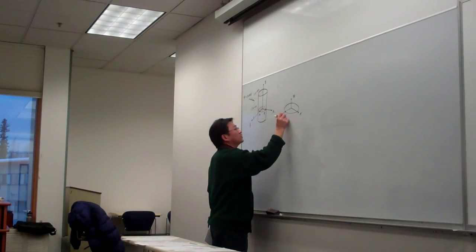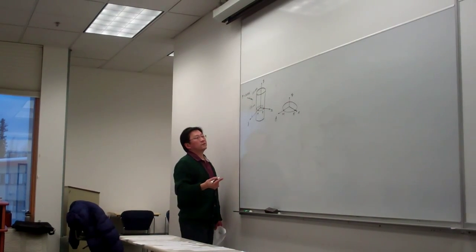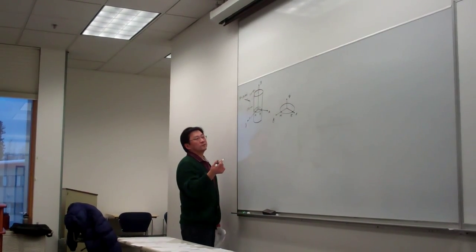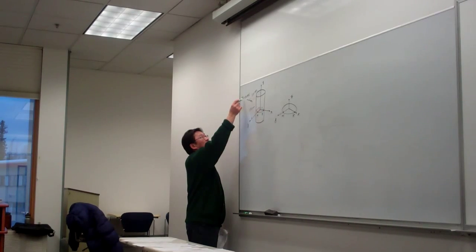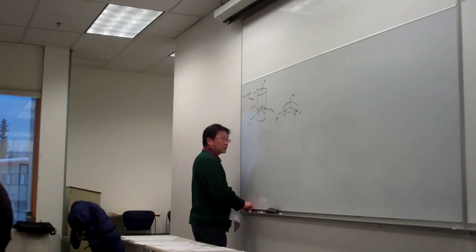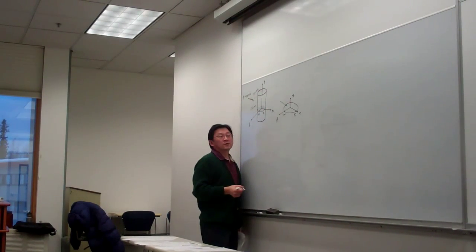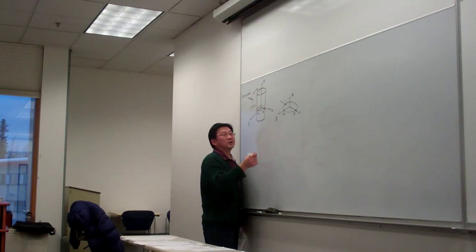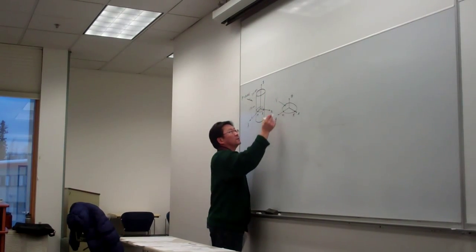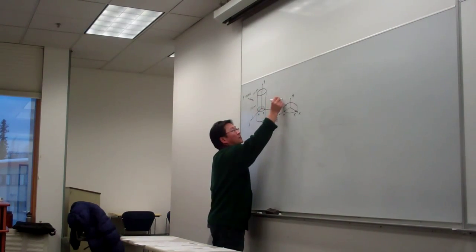This is point H, this is point K. To calculate the first one, we find the reaction force first. P is applied at 10 kilonewtons, so on this section, in the x direction, we have the reaction force parallel to the cross section. Here we use V, and in magnitude, in equilibrium, it equals 10 kilonewtons.